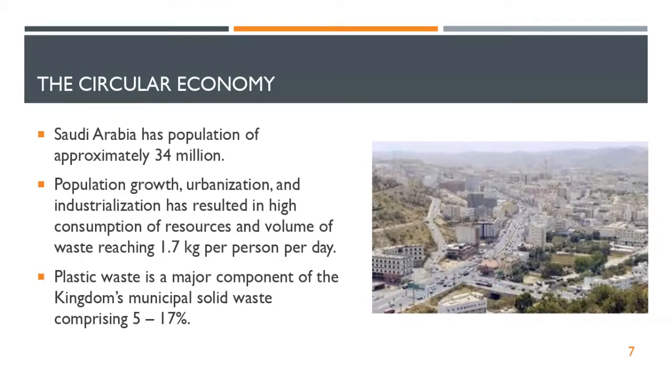So to answer your question very specifically, by choosing the right petroleum fraction, you can tailor the properties of your asphalt binder before the rubber crumb is added to it. You can test that in the lab, and I'm sure that Aramco did that before it built its test section of 160 meters. But ultimately, there is no replacement for field trials. You need to know that.